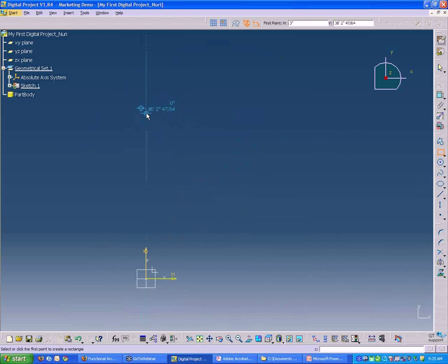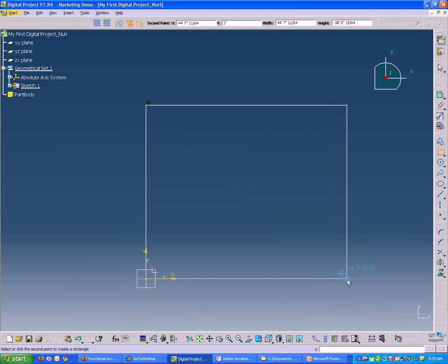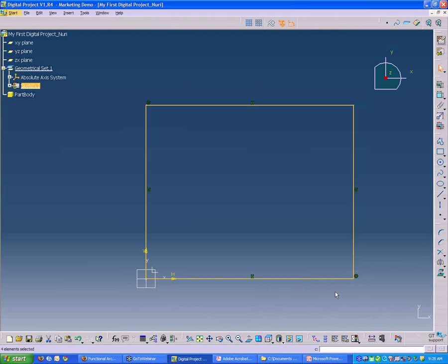So in this case, I'm going to wait until this vertical dotted line is present, because it's going to link up to my vertical direction here. You'll see it kind of turn blue, and the vertical direction will turn orange. So I click that, and then I drag over and then you'll see the horizontal direction will turn orange. It's selected, and I'll get a horizontal blue dotted line indicating that it wants to create constraint.